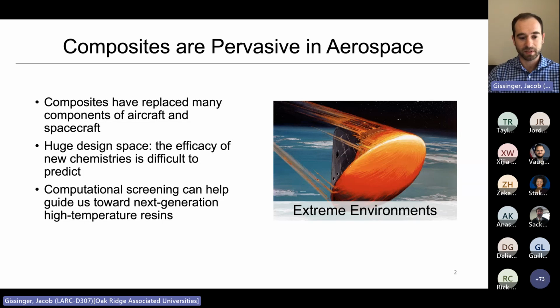So you may be aware that there was a successful uncrewed mission around the moon late last year called Artemis 1 from NASA. And here's an illustration of the Orion capsule as it's re-entering the atmosphere. The job of the heat shield is to protect it from the extreme temperatures that it is subjected to, which are upwards of 3,000 degrees Kelvin, so about as hot as it gets. And the heat shield on our Orion capsule behaved well overall, above expectations. However, there were some unexpected small behaviors, such as very small parts kind of breaking off as opposed to a uniform ablation of the entire heat shield surface. So that's something that wasn't predicted by the large-scale ablation models that the NASA engineers had. So that's something they're working to correct.